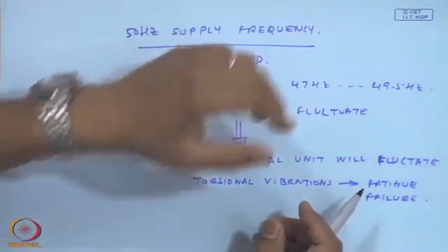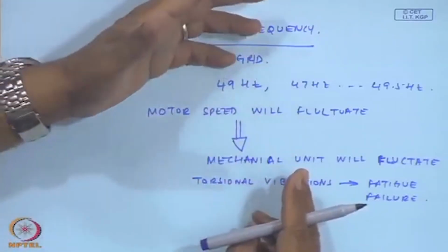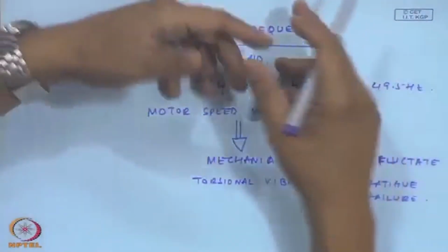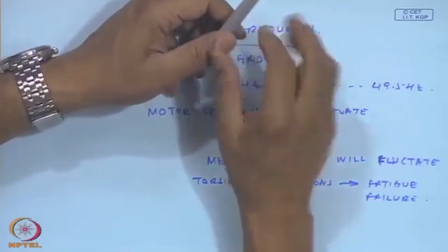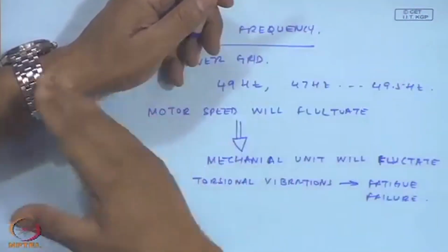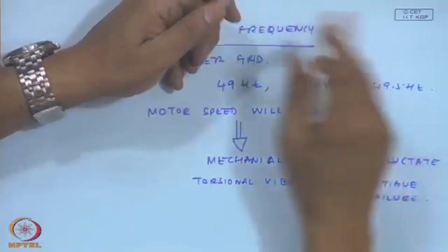And so, they have to monitor the 50 hertz. If you have ever been to a power plant, you will see they constantly monitor the supply frequency, or the power generation frequency, at 50 hertz. If I put in more steam, there have to be governors to limit it so that it will run at 50 hertz. Otherwise, if I do not govern it, speed will increase and the power supply frequency is going to increase. We all take it for granted, but a generator is supposed to run at the same constant speed. If I give in more fuel or more steam to a steam generator, it is going to speed up.